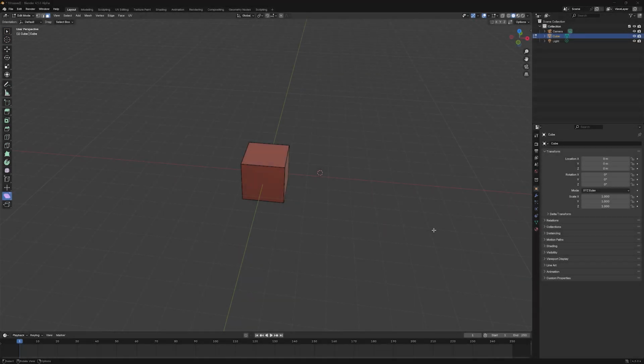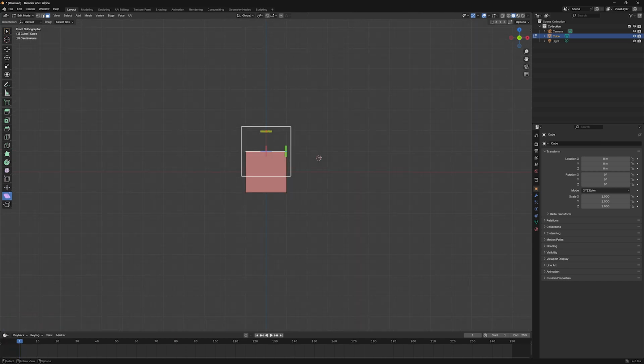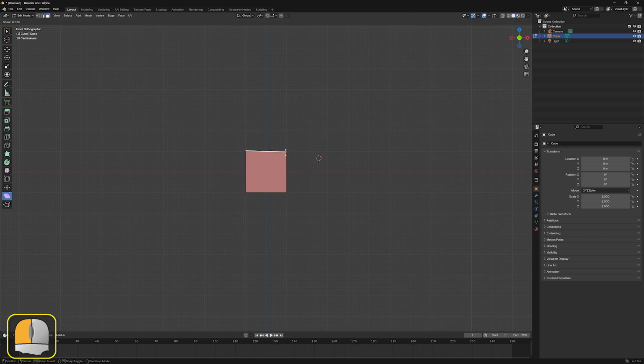The easiest way to use the tool is to start from the named viewpoint that will show the profile of the rotation. Here we have moved to front view to rotate the cube's selected face about the y-axis. As we drag on the green bar, the face rotates but also changes its own shape so as not to distort the width of any of the other faces.